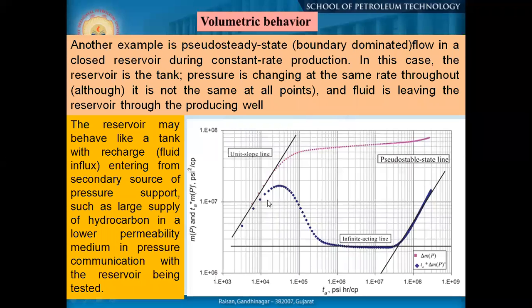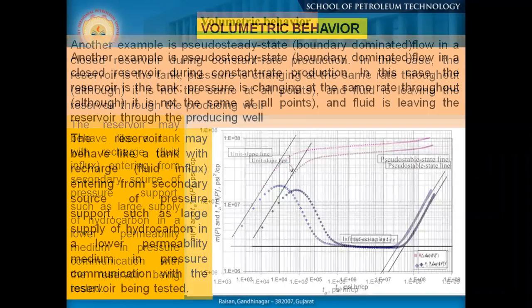So that means here we are considering the wellbore is only the tank, and here when it has reached your boundary, or the main reservoir is now not supported by maybe the aquifer, that means we have a half-hearted support, that's why we are getting another slope and the pressure is decreasing at a specific rate following a specific pattern, which is a unit slope, okay. So this is two domains of our infinitely acting reservoir, and then okay.